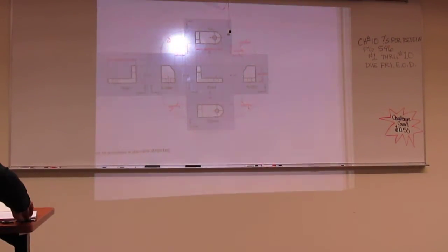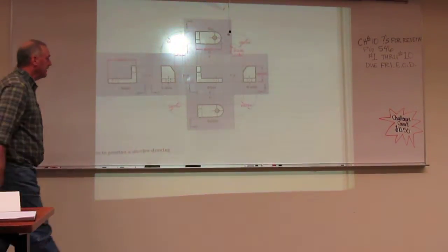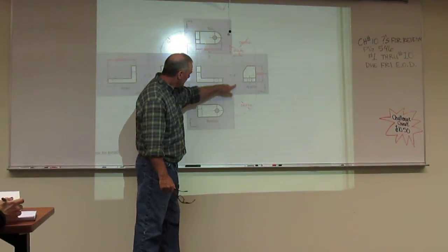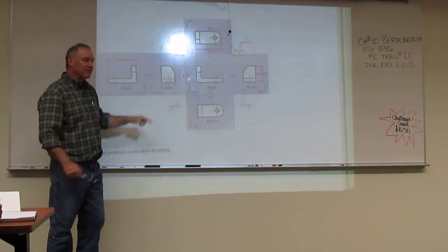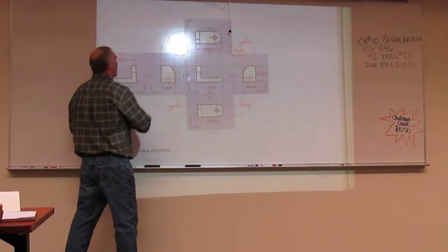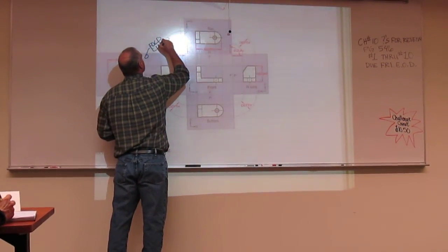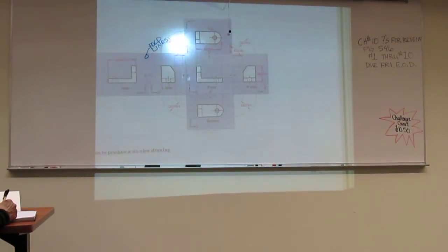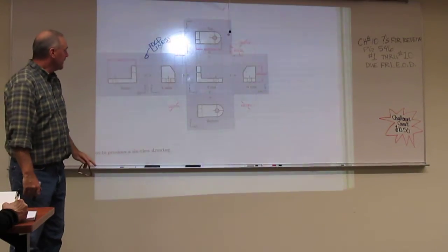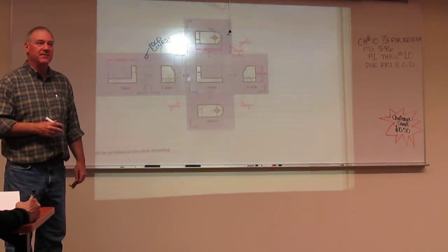Okay, so other things on the box to point out. We have a couple of definitions to go here. A new thing: these lines right here that are around here, we call these fold lines. And these guys right here are fold lines. These represent the edge of the glass box as you unfold it. So they represent where the planes are. Now you might think, why are they on there? They're on there because we can use them to transmit dimensions between the views.